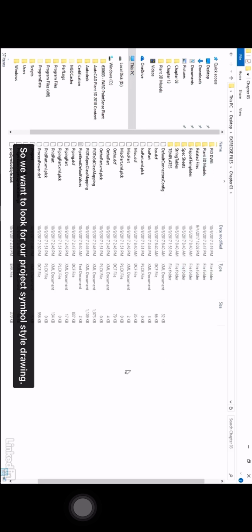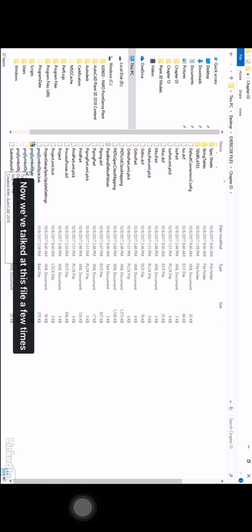So we want to look for our project symbol style drawing. Now, we've talked about this file a few times through the lesson already, saying that we cannot rename, delete, modify, or purge this file. And the reason is this is the file that contains all the information about the project. Now, when we actually go in to make changes to our project manager, the first thing that happens is the project symbol style drawing is opened, allowing us to permit changes. If we right-click and change the properties to read-only, that effectively locks the project manager and won't allow changes to be made at the project admin level.